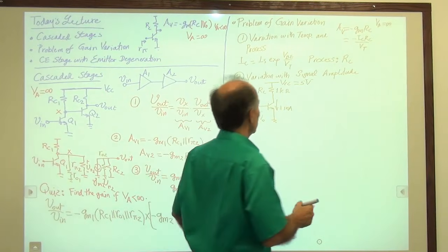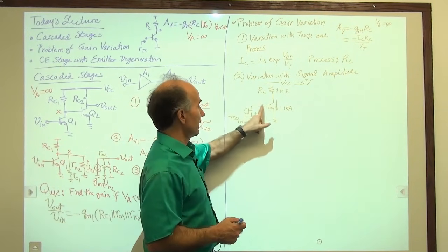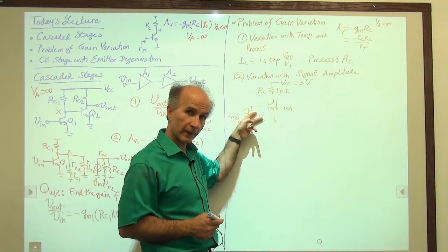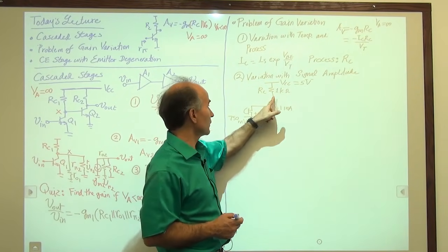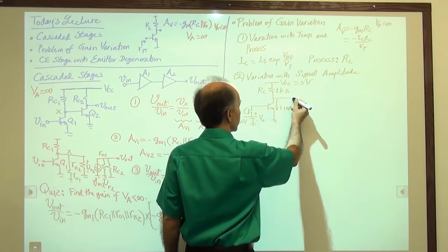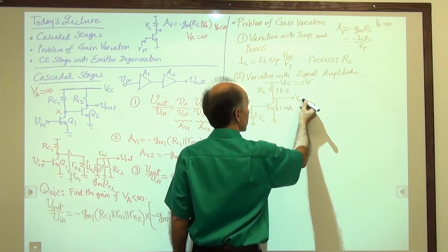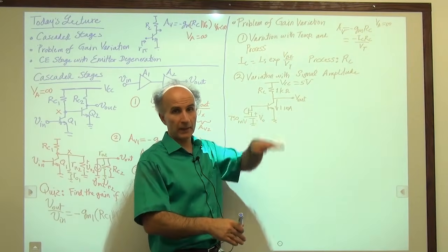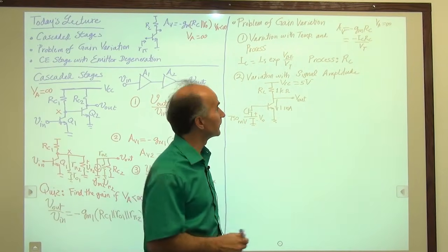Okay, well, let's try to plot the base emitter voltage as a function of time while the microphone signal is coming in, and also the output voltage as a function of time. Remember that these are always very good because they show us both the bias level and the signal fluctuations.